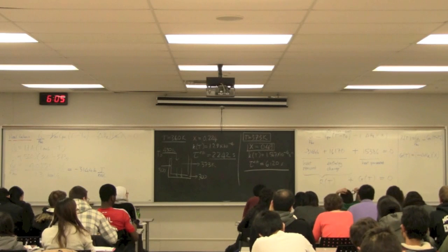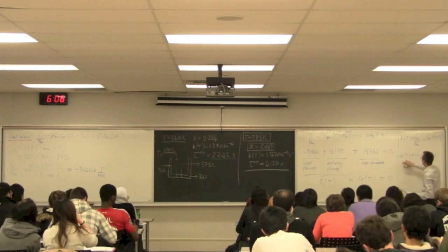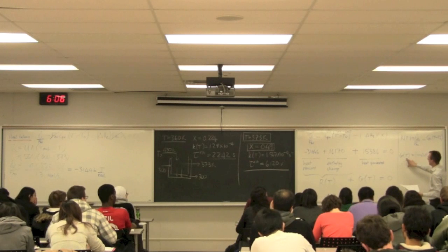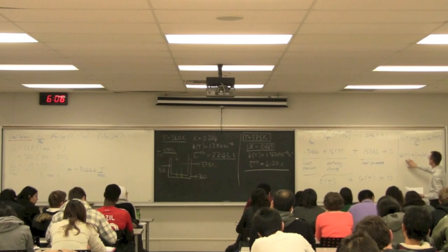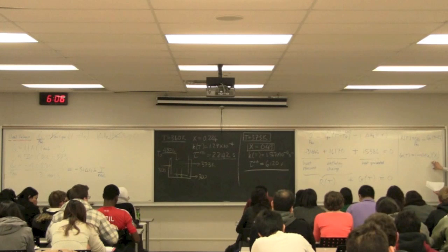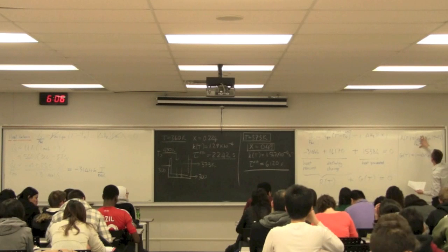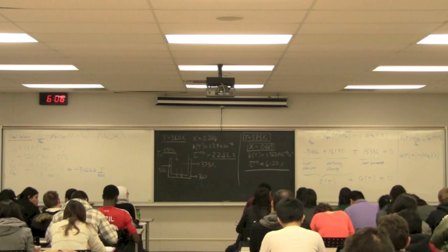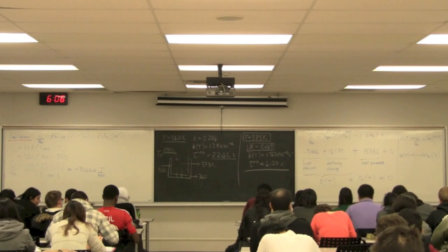So that's the generated heat, and we have to ensure that we handle all the heat that gets generated at a particular temperature. If I choose to operate my reactor at higher or lower temperatures, this G function will change. So whatever heat gets generated by the system, I need to ensure I remove it in two ways, either externally through Q or through this enthalpy term over there. And really the only way I can adjust that is by adjusting T naught.